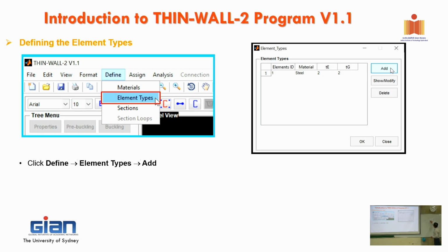So it means that in here, somehow that area is overlapped, but this area is missing. But in general, the total area is roughly the same, roughly accurate, but it's not 100% the geometry of that one. But as I said before, you can assign this one 2 millimeter, you can assign this one 1 millimeter by selecting different elements, or even different material as well. In a composite structure, sometimes you use top flange in steel, and the web in aluminum, for example. You can do it.